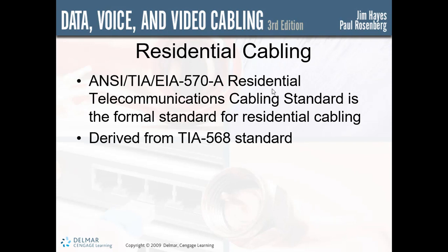100 meter length maximum. Two grades of cabling jacks. Distributed devices are specified grades 1 and 2. Grade 1 cabling may be Cat 3, which likely will not be used. Grade 2 must be Cat 5. Cat 5e would be recommended. Grade 1 outlets terminate one 4-pair of UTP cable and one 75 ohm coax cable. Grade 2 outlets can terminate two 4-pair cables.